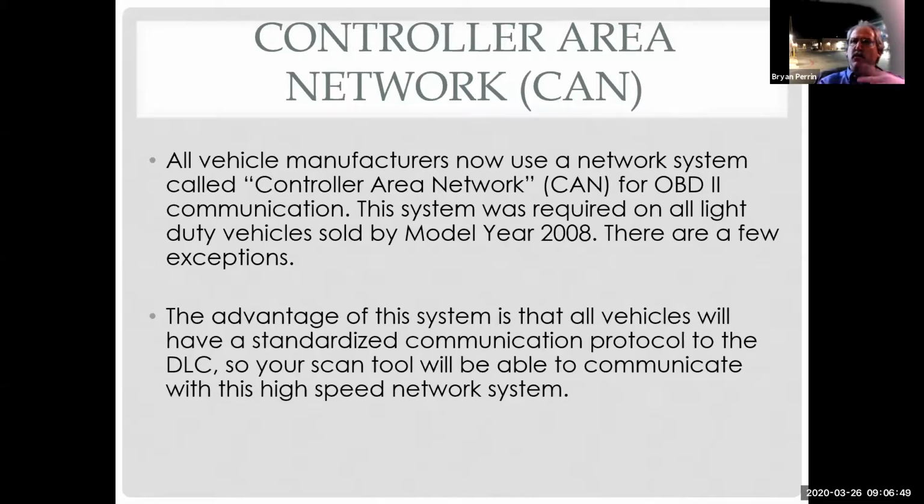Also, the refresh rate, meaning the time that it takes my scan tool as a module to ask for information from the engine module and get the information back, is much faster. On an old system, say a European system using ISO 9141 like BMW, it could run 700 milliseconds to 1.2 seconds for my scan tool to ask for how hot the car is running, and the engine computer to come back and give me a number.